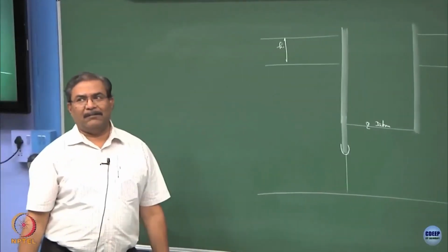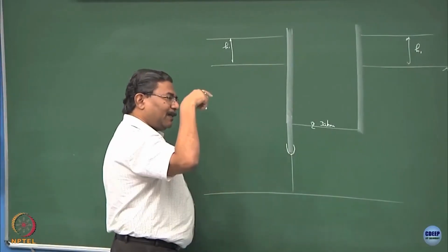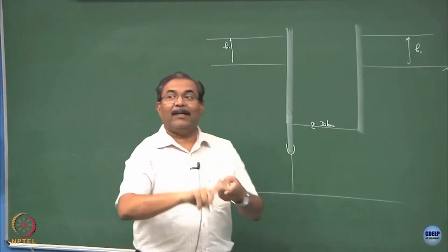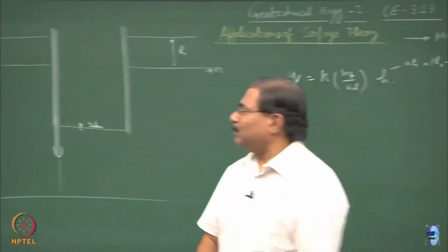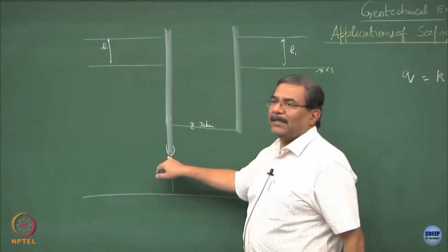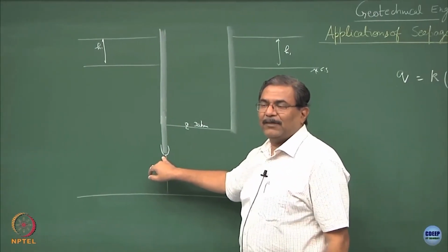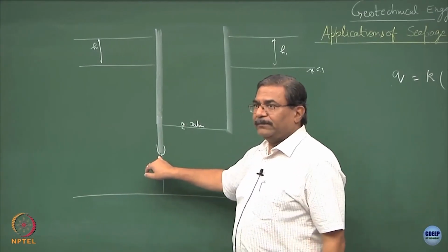I said no harm, but look at this point. This point is acting as a flow line also, it is acting as an equipotential also. You are defying the phi perpendicular to psi concept. So these points are known as singularity points. That means we do not consider them in analysis, but you can't defy them also because they exist. Fine, clear.